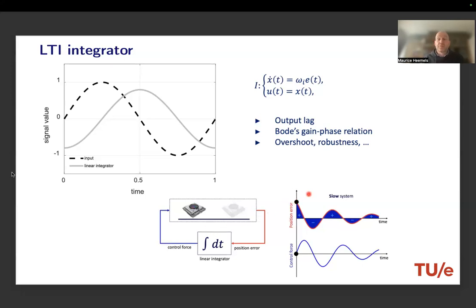Initially, suppose there's a certain positioning error. The integrator starts integrating, and at some point the position error is 0, but now the integrator buffer has a certain positive value. If you couple this back with a negative sign, that means there is a buffer accumulated at this point where the error is zero, we are perfectly where we want to be, but the integrator still has this buffer, which is going to cause overshoot. It's going to push us through the zero error point and cause overshoot.